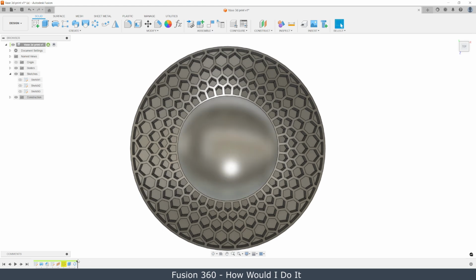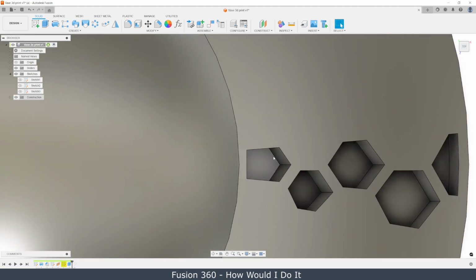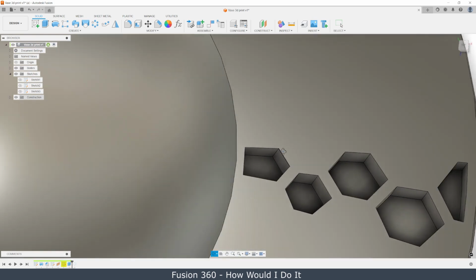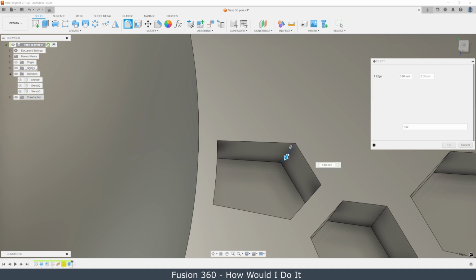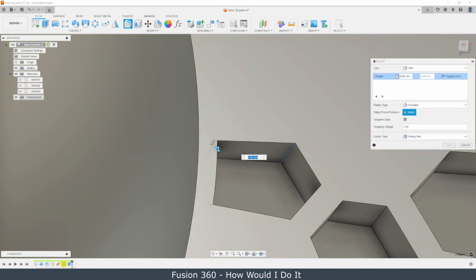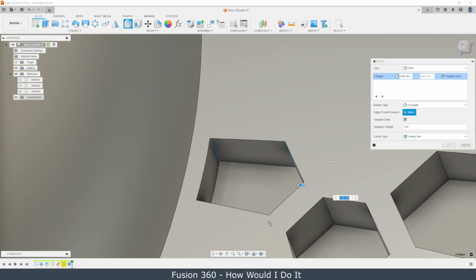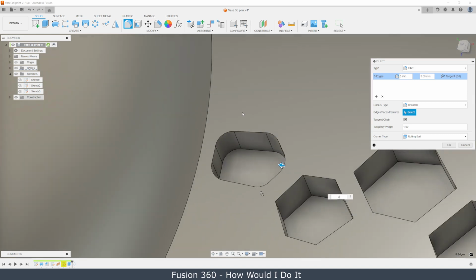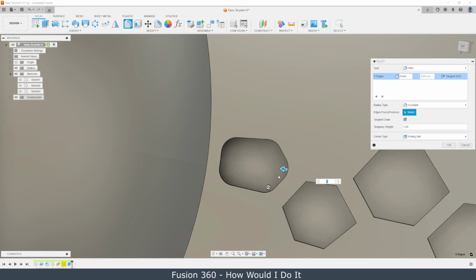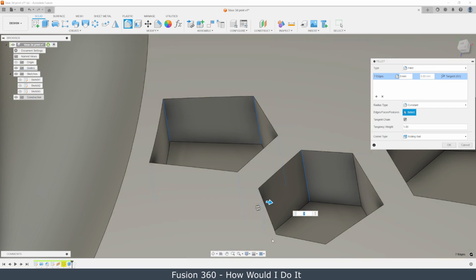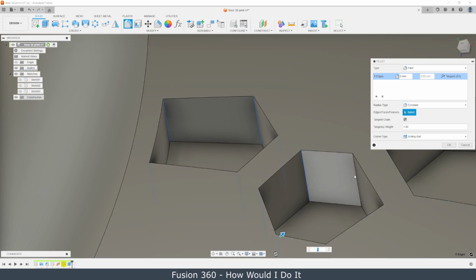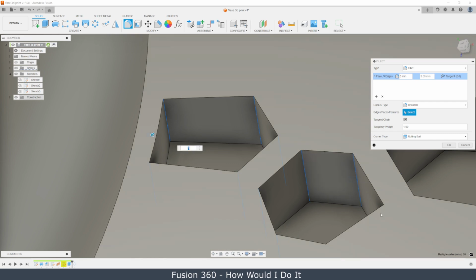So we will go back in timeline here and we will add fillets to these edges. Let's see what fillet would be okay. Fillet, radius 3 seems okay at this point, and go further with selecting of these edges.